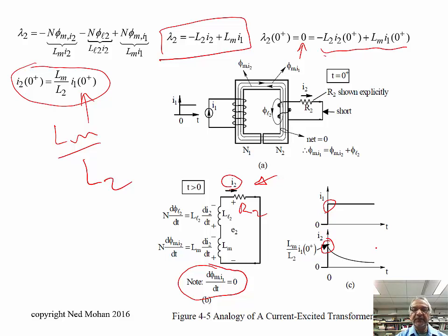And we'll see in vector control, we do not want that to happen. Okay, so here also, if you can insert a battery which opposes the drop across this resistance, we can avoid or prevent this I2 from decaying out. So essentially, we are adding a battery, so to speak, to prevent that from happening. And how that happens, we'll see.